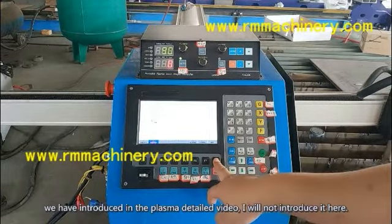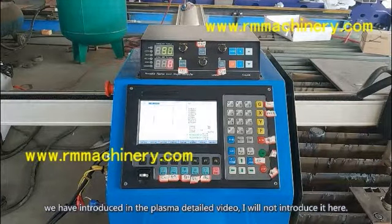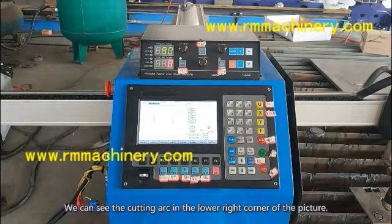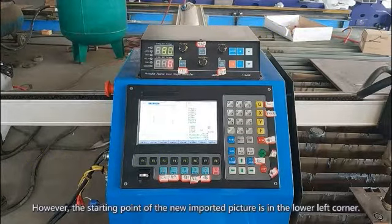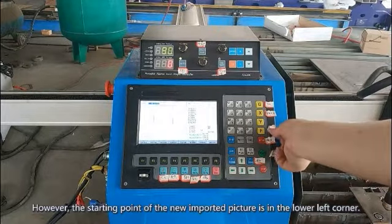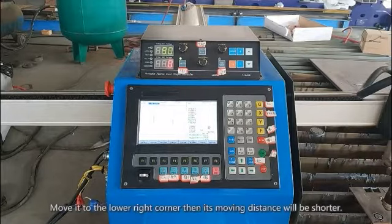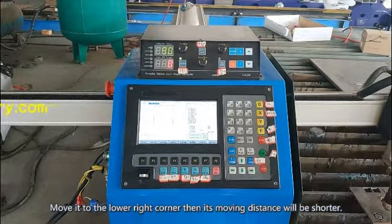We have introduced this in the plasma detailed video, so I will not introduce it here. Next step, we choose the starting point. We can see the cutting arc in the lower right corner of the picture. However, the starting point of the newly imported picture is in the lower left corner. We can change it when cutting. Move it to the lower right corner, then its moving distance will be shorter.